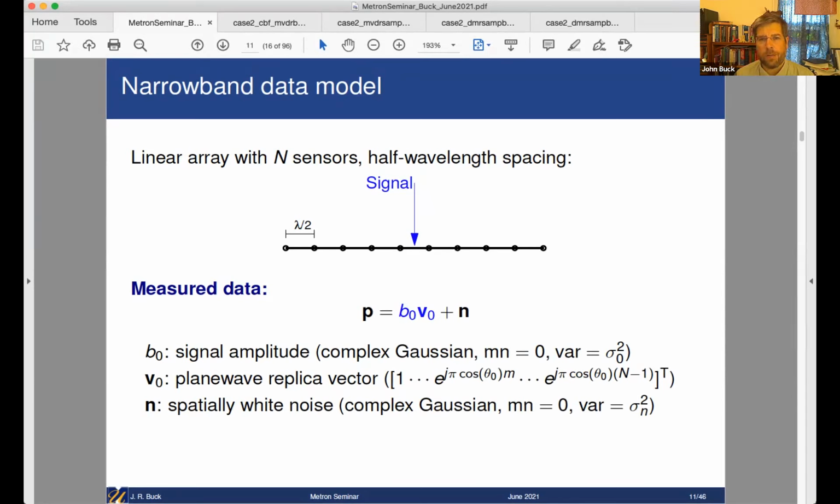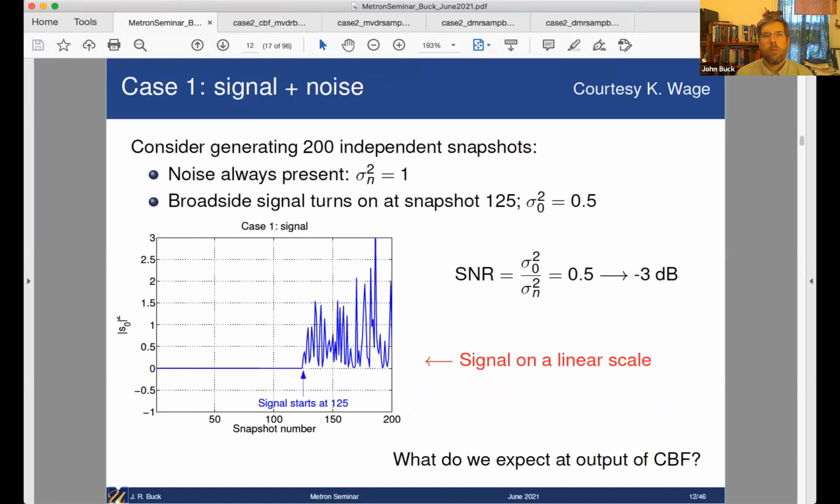So we're often trying to estimate where the sound is coming from in the presence of a varying amplitude and noise. And one of the most basic tasks in array processing is saying, can we detect something? When are we just observing noise? And when are we seeing a signal plus noise?